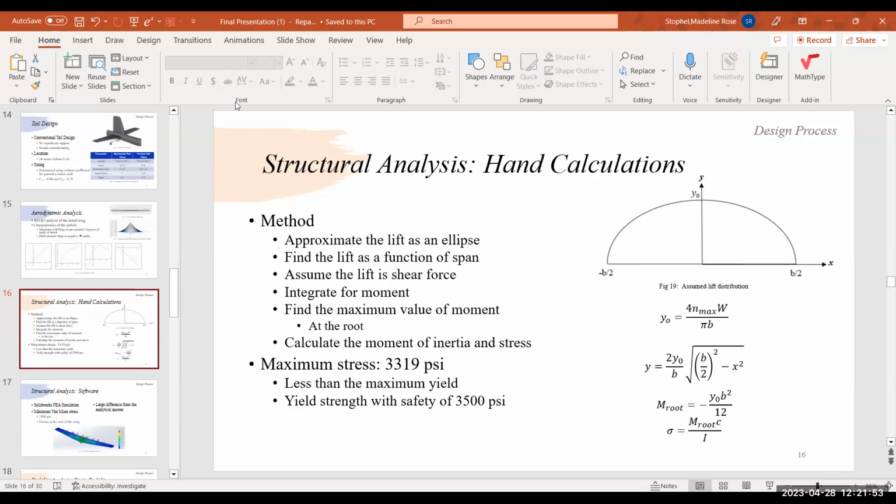Is there anything that could make you think that yield stress would be lower than what the spec sheet gives you? Absolutely, because it was printed using 3D printing methods, and the vertical stacking when printing a wing means that the lines of the 3D printing will be normal to where the shear is applied.